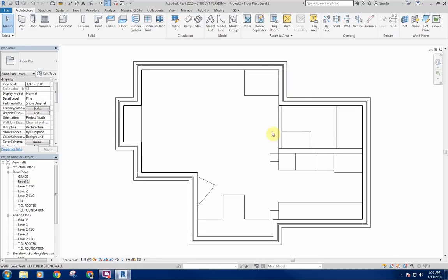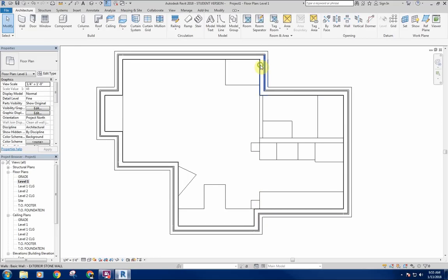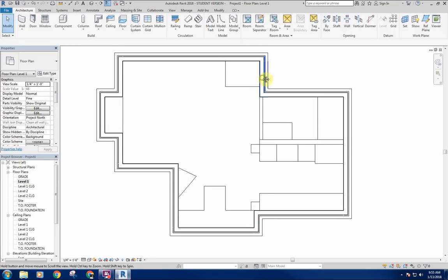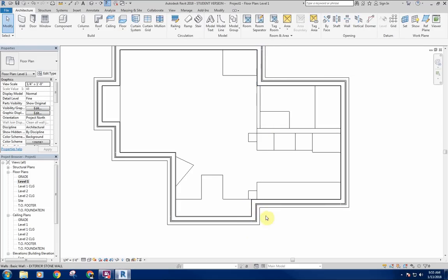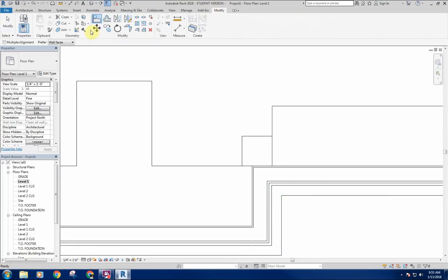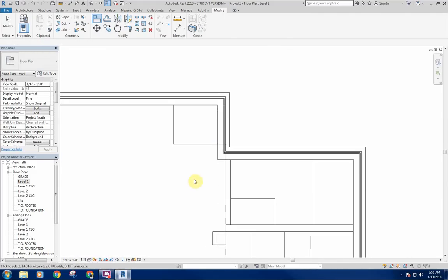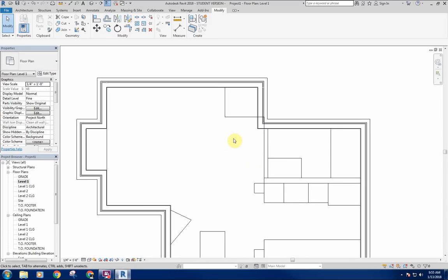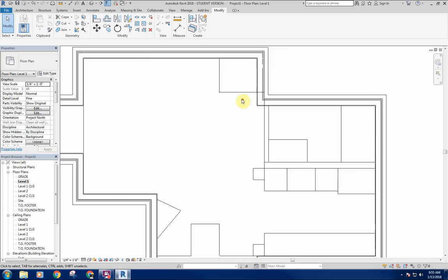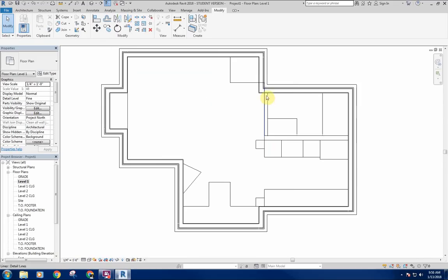Okay. So now, looking at this being offset from this probably doesn't work real well. So I want to bump this over here, and line this wall up with this wall. To do that, under Modify, I'm going to use the Align tool. You can prefer wall center lines or wall faces. Wall faces is fine. If I click the very edge of the drywall here, and click the very edge of the drywall here, it's going to jump that over. If there's a little offset here, that's all fine. Not a big deal. We'll just adjust our closet and stuff like that accordingly once we get into this.